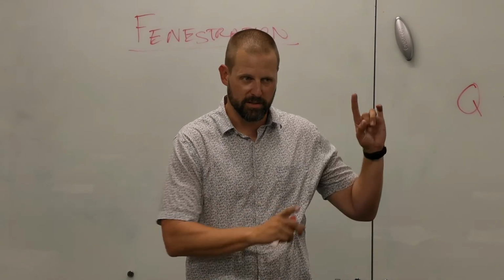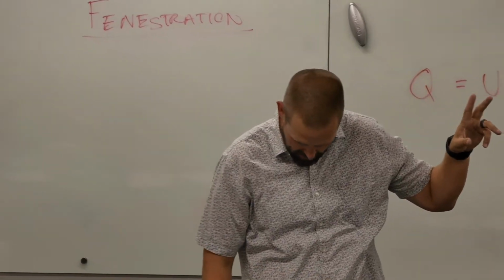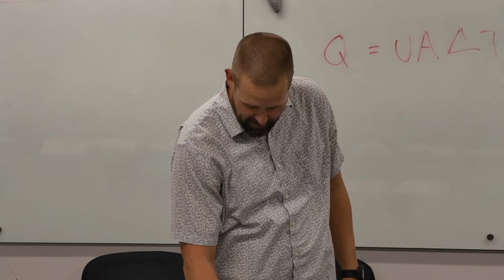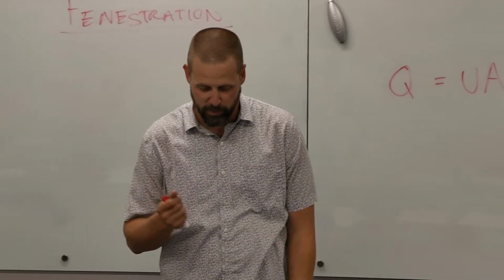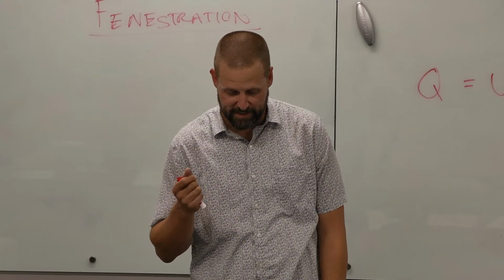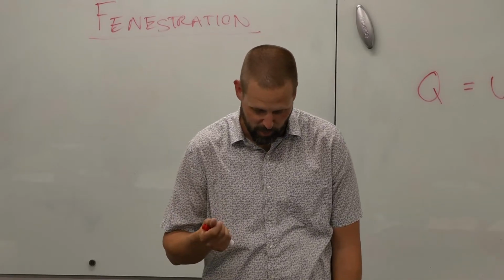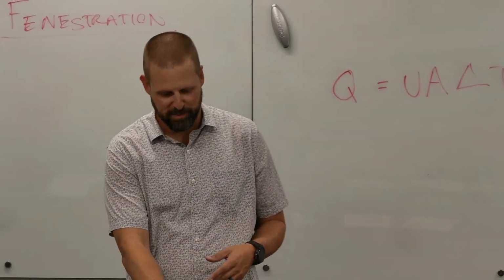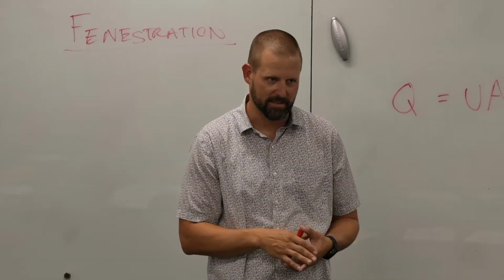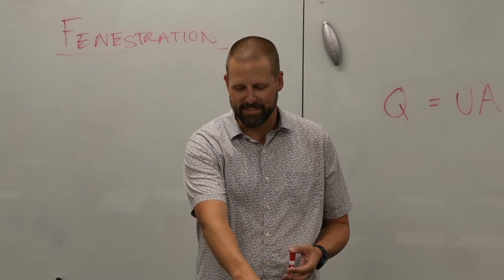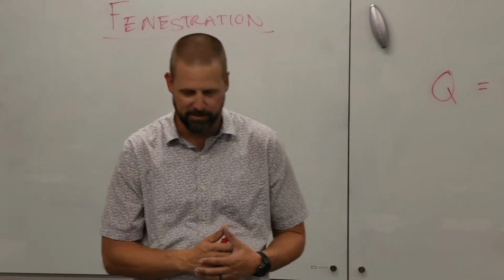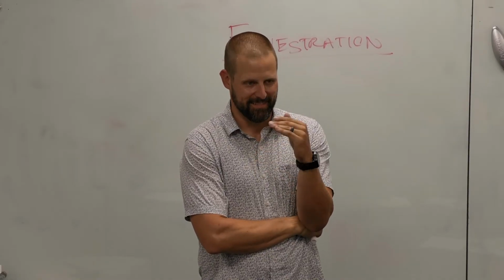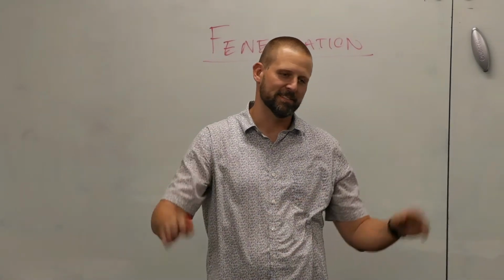So remember, single pane has a U value of 1 or 1.2, and a solar heat gain coefficient of 0.8-ish. The current prescriptive code requirements are closer to a U value of 0.47 and a relative solar heat gain coefficient of 0.31. So we've cut those in half, and they might even be worse than that. That's just what we did for a project. I think they're actually worse for that. That was an alterations project that we did with Gensler a few months ago. But they're like half of what they were. Okay, who cares? Let's go to compliance.